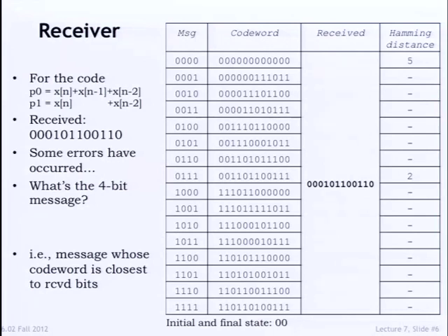What you'll do is you'll search over all possibilities. At least that's one way to do this in principle. Search over all possibilities for the code word here that's closest to what you received. Okay? The trouble is that's a lot of code words. It's a lot of code words, so this can quickly get out of hand. If you've got long sequences, which is exactly where you want to do convolutional coding, you've got a very long table. Okay, so you really want to find an efficient way to do this matching.